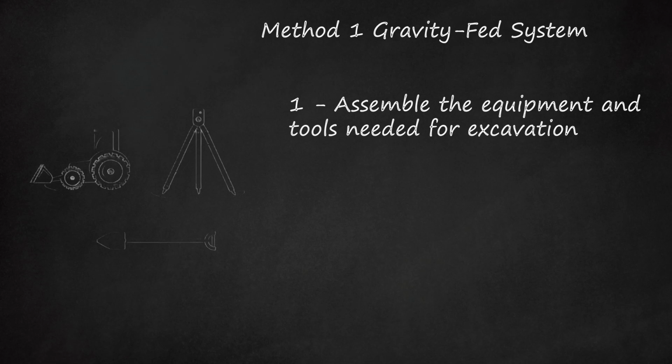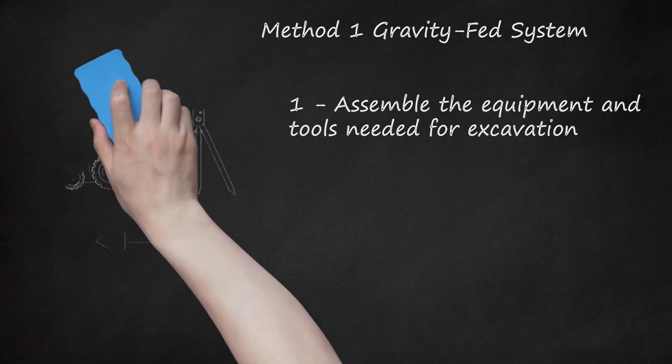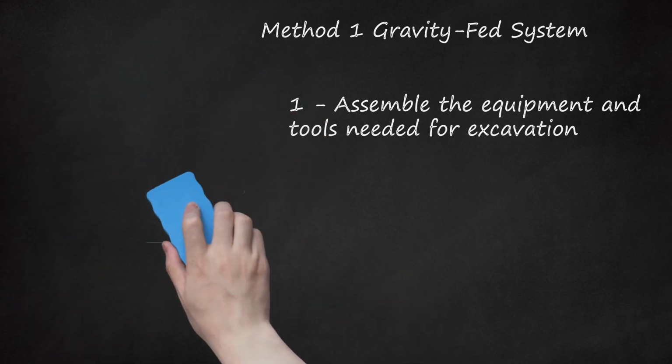Seal, for concrete, or silicone caulk, for plastic, to seal risers. Septic filter, Zoeller 170 or similar, if required. Distribution box, either concrete or plastic, if running more than 2 laterals.